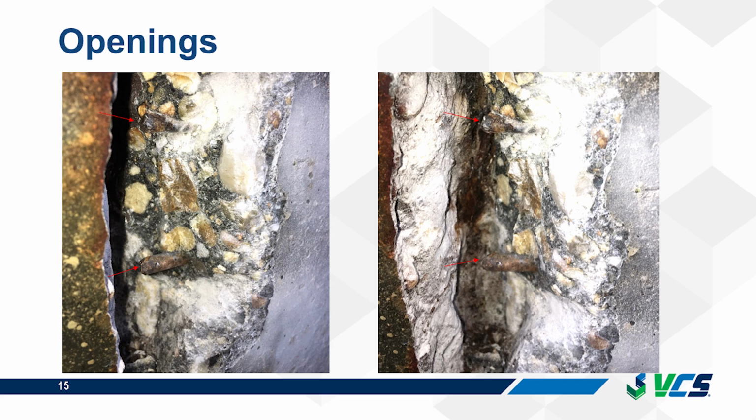The most important test that we did, and the most important from the structural engineer's point of view, was openings. Because before the investigation, there was a question of how much section loss was in the cracked piles. We did openings in the piles with cracks that ranged from 1/8 to 1/2 inch. And what we saw is that in all the openings, there was 100% section loss of the stirrups.